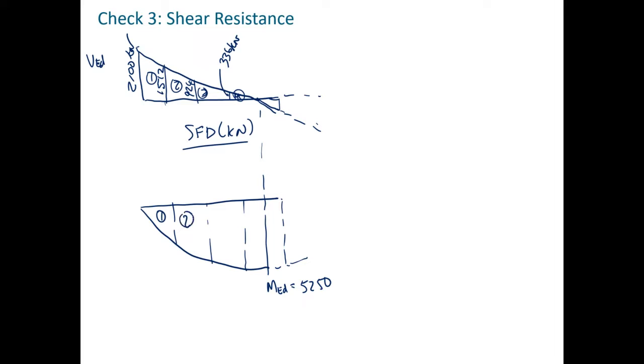Okay, so panel 1, 2, again 3, and 4. We've just worked out that one as 2528 kilonewton meters. And then we can do the same as we've done for that one for all the rest of them. When we get 4,223 kilonewton meters, and then 5,115 kilonewton meters. So you need to learn how to do these if you haven't already learned how to do them.